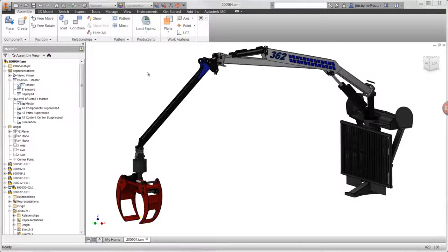Welcome to this demonstration of Autodesk Nastran in Inventor. During this video, we're going to find out if the material we're using for the crane does not yield and ensure the model will not buckle under a 20,000 Newton load as a factor of safety. Buckling may occur in areas of the design where there is a loss in stiffness due to compression. It is often dangerously overlooked and can be analyzed right here inside Inventor.